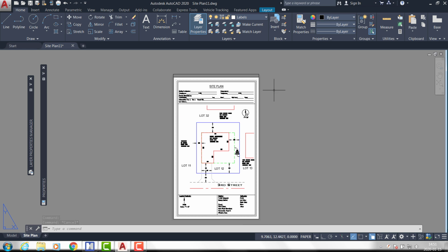And now what we want to do is find a plot command. So that's something that you can type in on the command line. The Quick Access Toolbar usually has a printer icon up here indicating that you're going to be executing the plot command. So plot in the bold letters is the command that you would type in on the command line. So AutoCAD is, as a reminder, a command-driven program. So all these commands that you see in the menus here can also have their equivalent typed in on the command line. Okay, so we're going to print this to PDF.